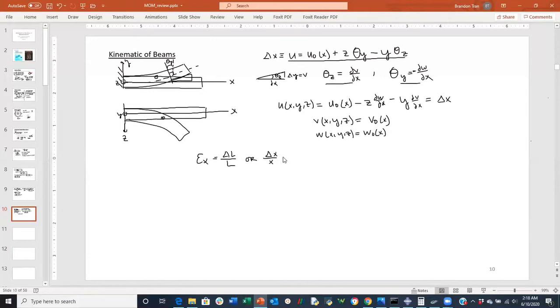So that's how we establish the strain. We equate that, and this equation is established using an infinitesimal assumption for Green-Lagrange strains. I won't go into detail about that, but essentially the equivalent for normal strains in the x direction would be the displacement in the x direction, partial with respect to whatever position x direction you choose.